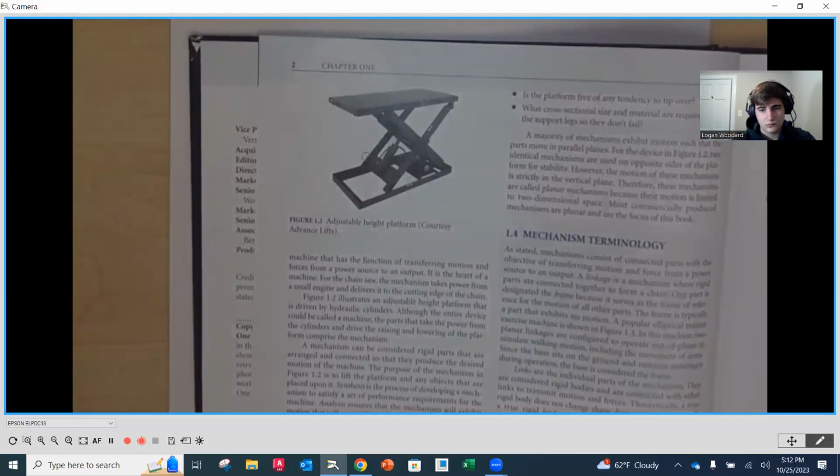Or if we look, there's a cylinder here, okay? What does the travel of that cylinder have to be? What does the stroke of that cylinder have to be to obtain this up and down that I have? That's a kinematics problem. But notice we're not talking about what size is that cylinder, how much force does that cylinder have to have? No. It's just travel, displacement, position. We're starting there. First, it's like those initial questions that we're asking about that final design, that final objective that we want to achieve, okay?